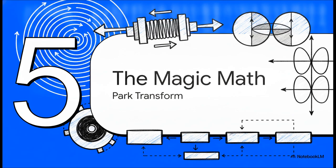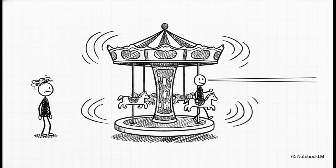But you might have caught a specific term I just used there, the Park transform. How exactly are we isolating those currents in the first place? Let's lead right into our final technical section to look at the specific mathematical mechanism making all of FOC possible. The Park transform is quite literally a mathematical time machine. It was invented all the way back in 1929 by Robert H. Park. And what it does is take a rapidly alternating three-phase AC system and transform it into a stationary two-quadrant DC system.